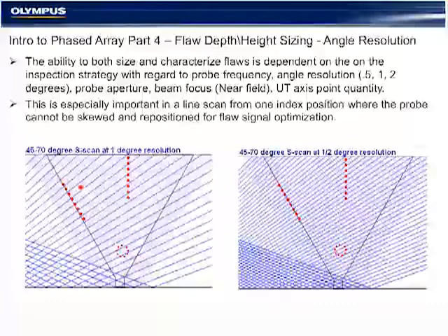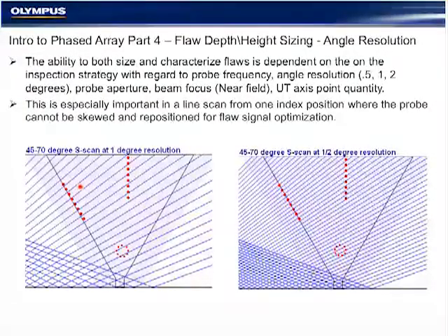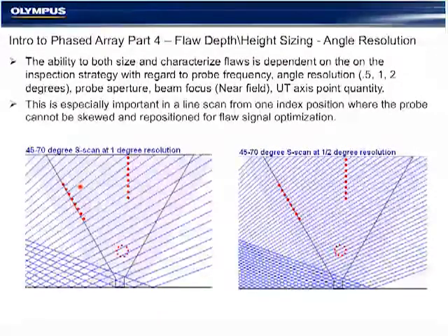In both cases, for our typical welds, they would provide 1 millimeter sizing accuracy, which is often a common benchmark for what people would expect paying for phased array inspections. With the use of TOFD, that can be improved. In the type of material, carbon steel, we would expect 1 millimeter accuracy for length and depth height sizing if we had a good plan and a good calibration strategy. The thicker the material gets, the more accurate that becomes.